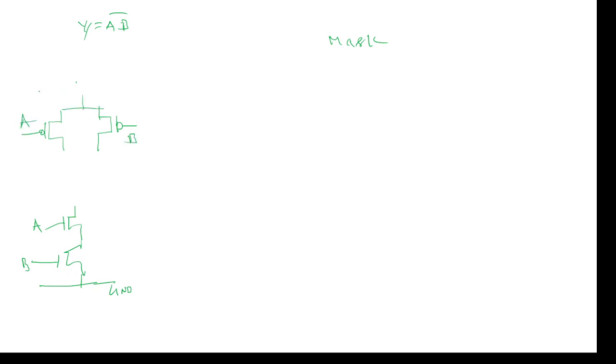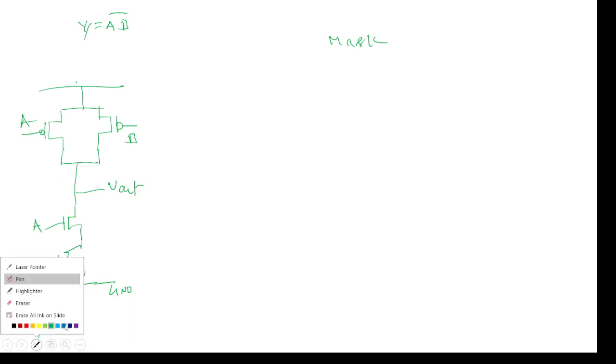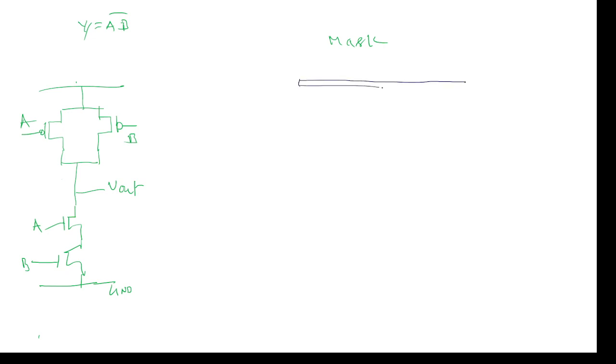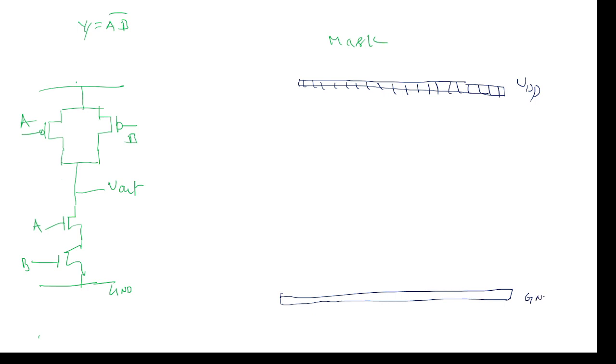So this is the supply VDD, and in between the pull up and pull down network we need to take the output, then only we can get the output easily. So now I am going with blue because metal is required, metal is blue color. The mask symbol for metal we have seen already, we have discussed. The box containing straight lines is the symbol for supply VDD. So this is VDD and this is ground. This is ground. This is ground. So it is a ground.